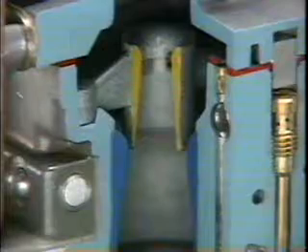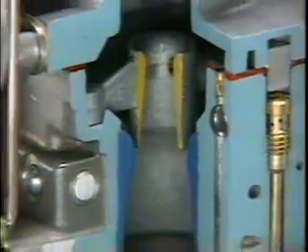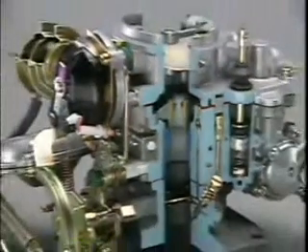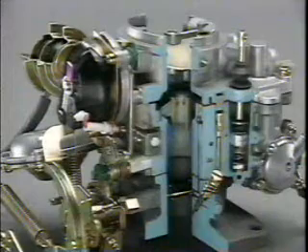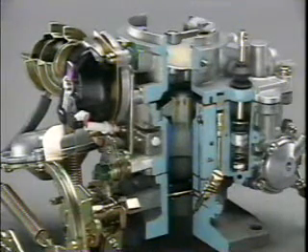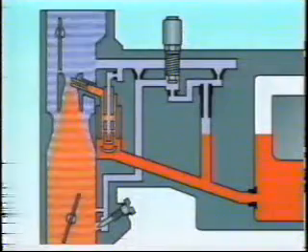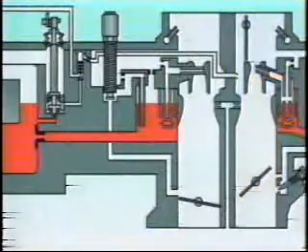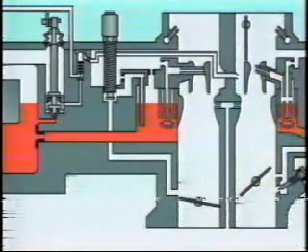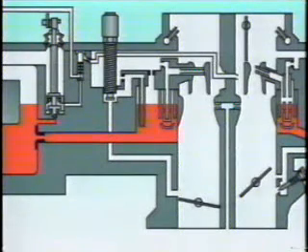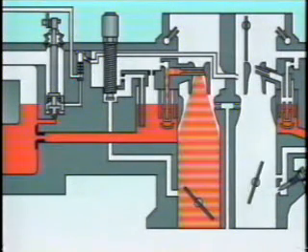This is how the air-fuel mixture is regulated during idling, and at low and medium speeds. However, this alone will not produce the power needed during high-speed operation. This is why the double-barrel carburetor has a secondary barrel. The construction of the secondary barrel is the same as that of the primary barrel. It has a high-speed circuit, which is its main circuit, and a low-speed circuit which prevents the mixture from becoming too lean when the throttle valve opening on the secondary side is small.